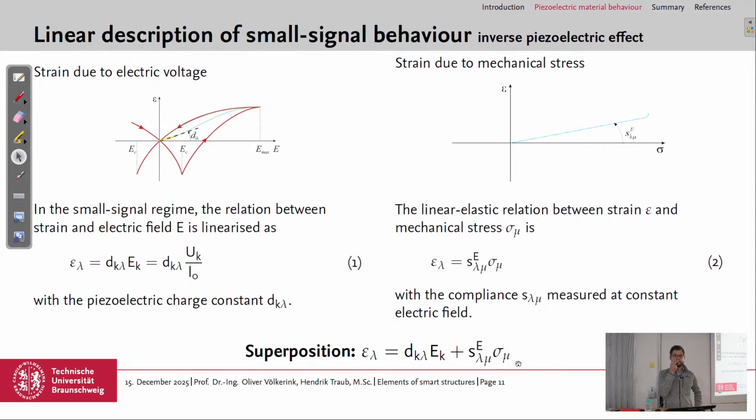What is causing this mechanical stress? For example, in the application, the external loading. But isn't the electric voltage itself causing the inverse piezoelectric effect, like electric voltage causing the stress? So they should be equal, right? Why are they superposed? It depends on the boundary condition, I would say. If you have the piezoelectric material not integrated into a material, and no clamped or blocked boundary conditions, then it could move freely and does not build up any stress.